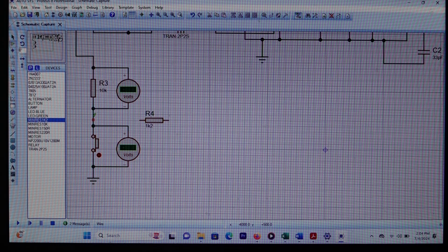And I told you that whenever you have a design where you want to use a digital sensor, and that digital sensor does not have a library, and maybe you try to find some other libraries to add into Proteus and you fail, or you didn't find it, then you can use this pull-up resistor network to demonstrate how your system will work. Similarly, you may use either the pull-up resistor network or the pull-down resistor network.